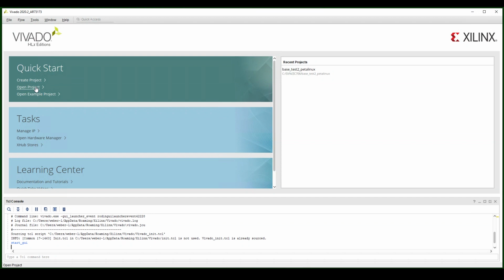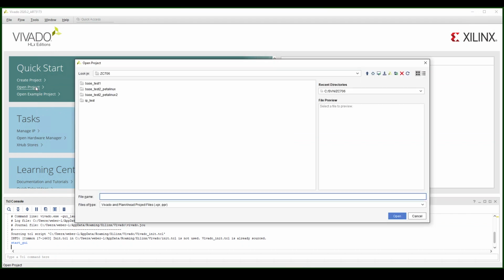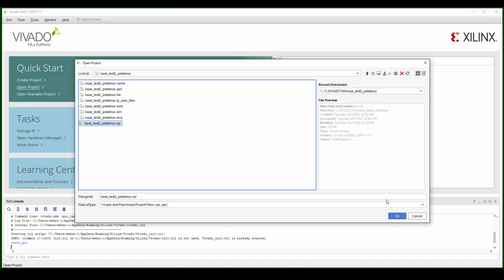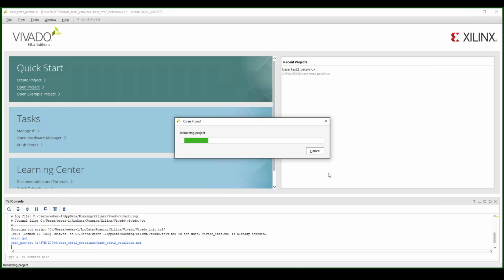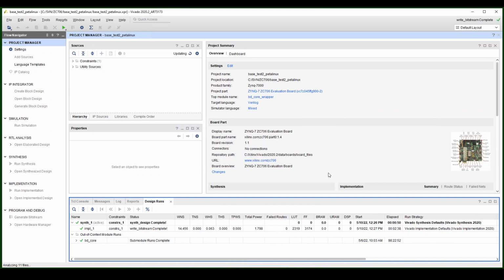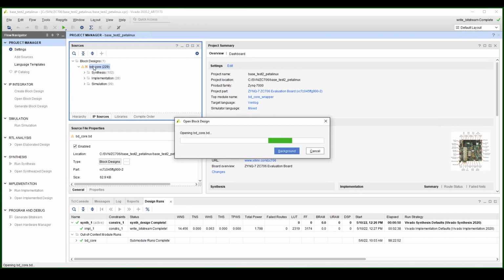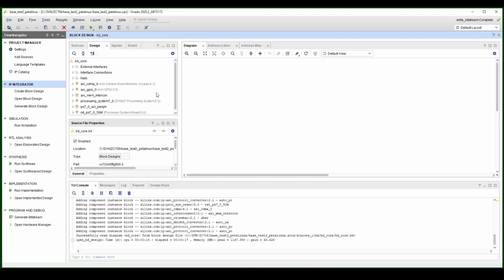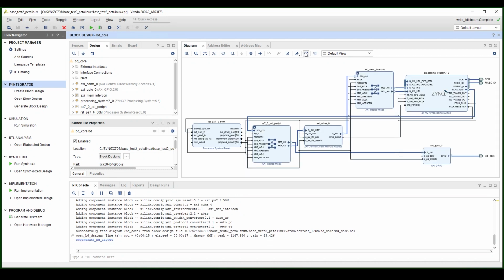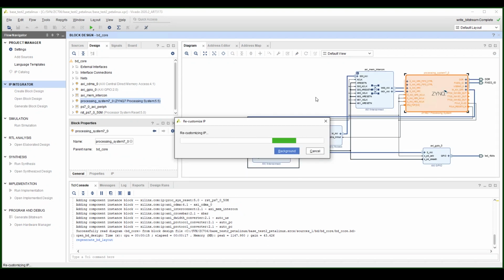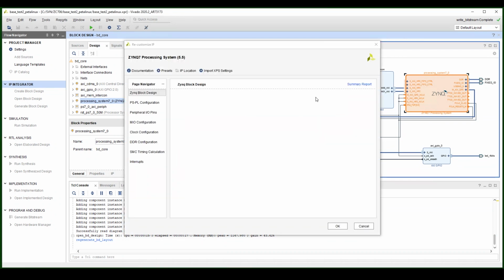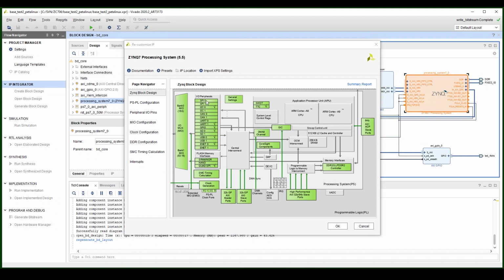Now let's start the project. So previously we built the bare metal basic ZC706 project on the PetaLinux platform. The ZC706 already has lots of devices, but there's no SPI in the design. So in this video, we're going to enable the SPI hard IP core in the Zynq core.